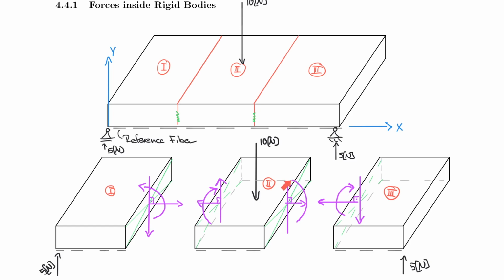We don't know if this is rotating clockwise or counterclockwise, but you can say, hey, there's a rotation in element 3 that actually rotates clockwise, therefore this needs to be counterclockwise. Likewise, you could use the argument that element 2 has to be in balance in total, and if this is rotating clockwise, then this one here has to be counterclockwise.